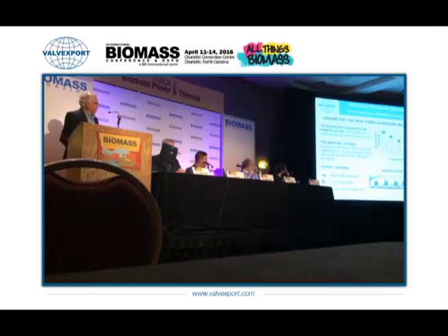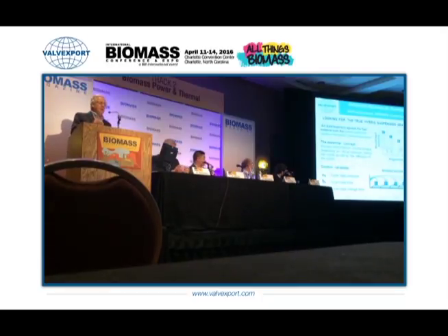The control variables are PS, and we can see a little graph here of the time of a cycle. We call the cycle in the automated system the time between startup at a certain pressure and then step by step lowering it down to the final value of that cycle, and then going back and repeating it over and over. And by controlling these three variables, you can control the position of the whole biomass over the whole grate.